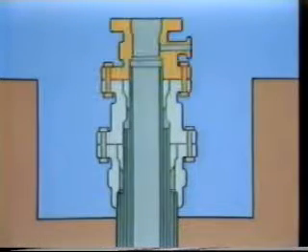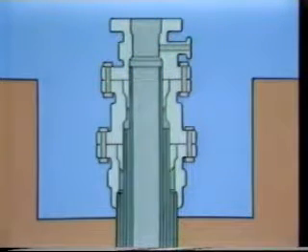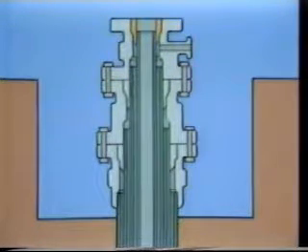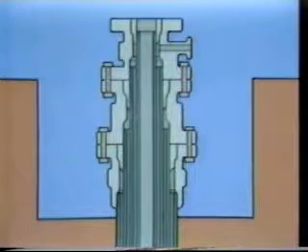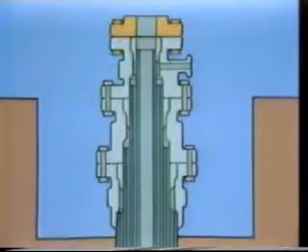The tubing head performs a function similar to the casing head, in that it accommodates a tubing hanger, which usually screws onto the top of the tubing string or strings and seals off the tubing casing annulus with metal-to-metal and/or rubber sealing elements. An adapter or bonnet provides a transition from the tubing head to the arrangement of valves and fittings located above the casing and tubing head, which are used to control flow.